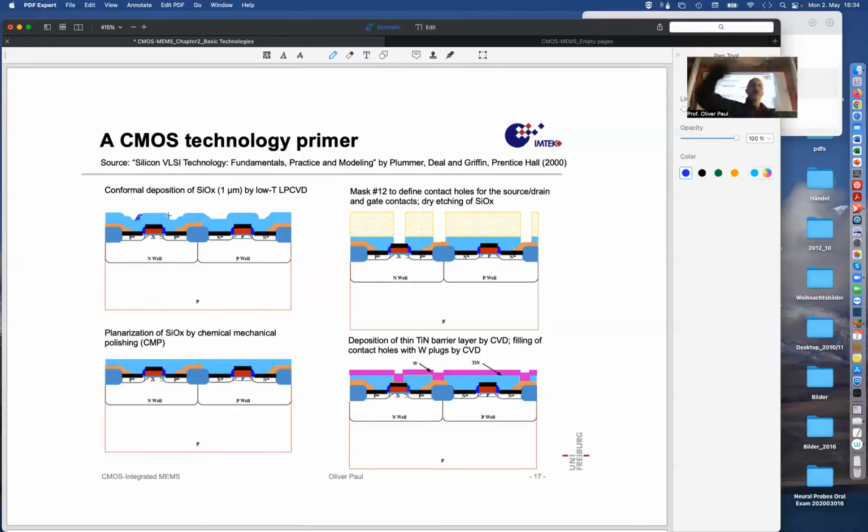Now, if you have metal lines running over that surface in this in-plane direction, and then there are these sidewall spacers of metal running into the plane, all those metal lines are short-circuited.